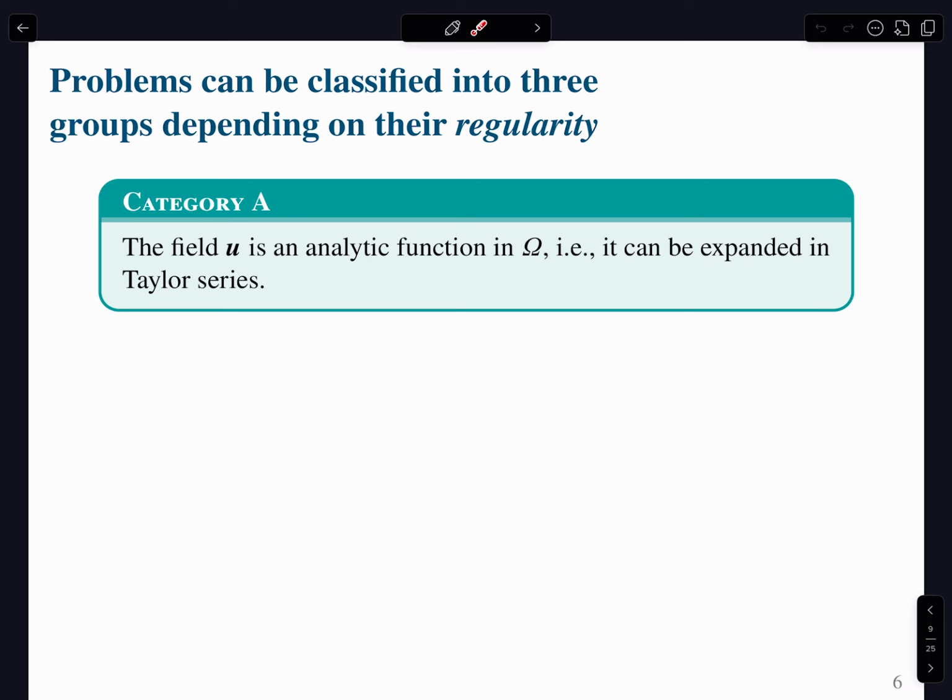So then you can think, well, let's try to think about a classification for all the problems based on the regularity of the solution. And by that I mean, if we can write the exact equation, that exact displacement field is going to live in some Hilbert space, right? And so if the function is very, very, very smooth, that Hilbert space is going to be of order very high. If it is not smooth and there is some sort of singularity on the domain, that is going to lower considerably the space, the Hilbert space, right? The order of my Hilbert space.